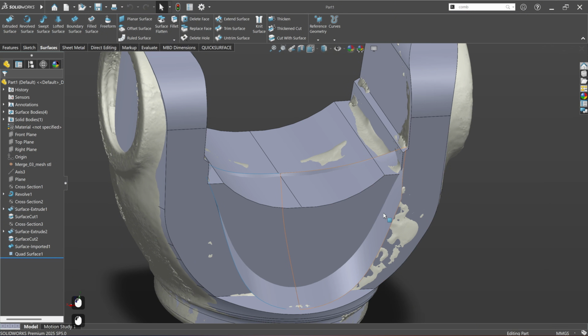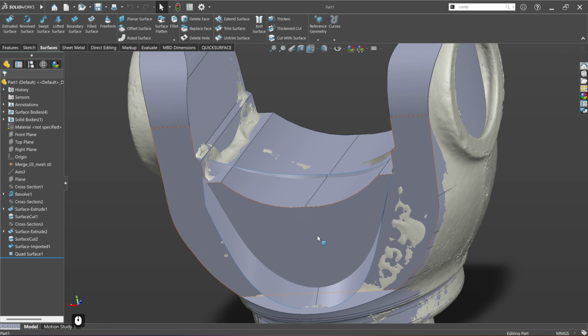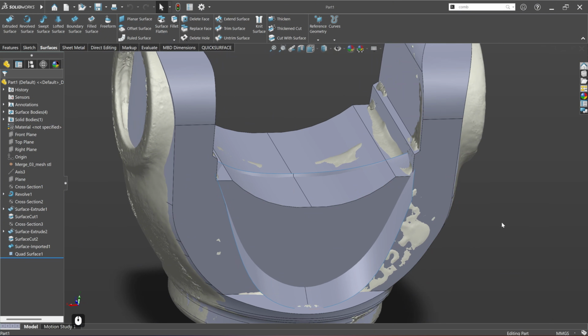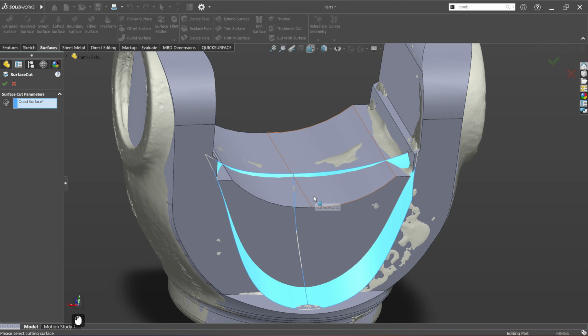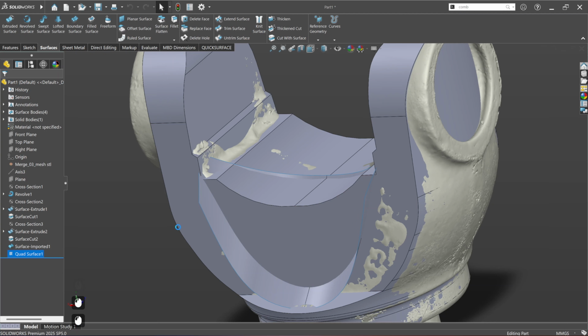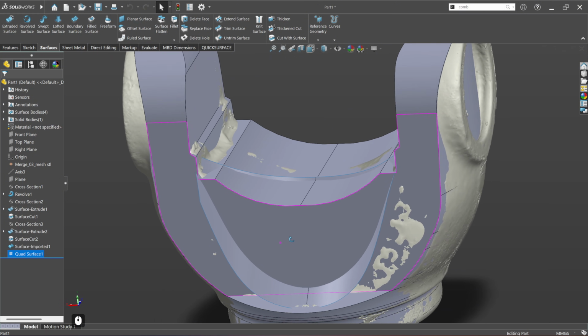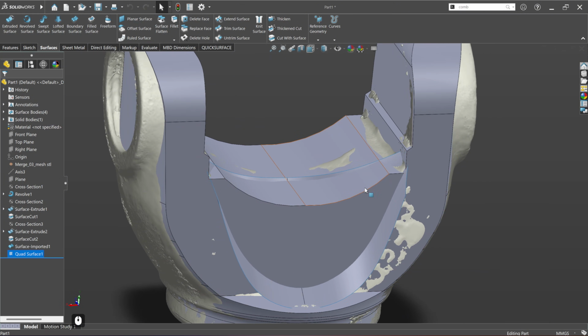Okay, once we have this surface created, we need to trim this away from our main solid body. How can we proceed to this? So based on previous actions, logical would be to come over this quad surface, set cut with surface, and click OK. But well, this doesn't work just because Solidworks doesn't have same trimming tools as we have in our standalone software. That might be done there just absolutely easily. So we will need some different approach here.